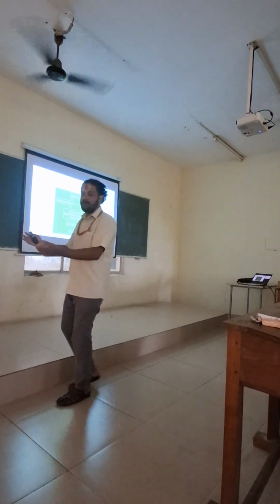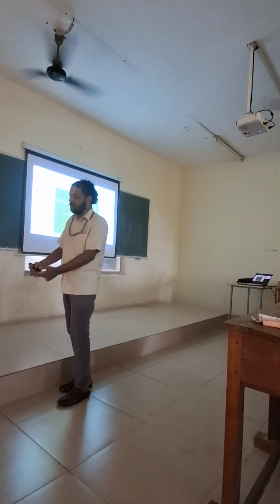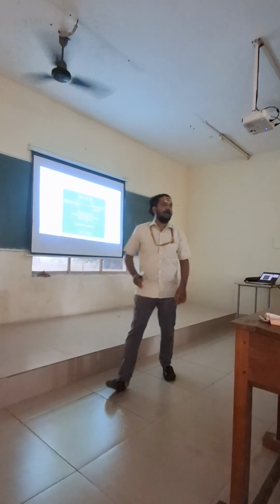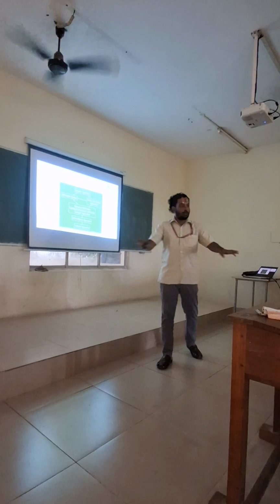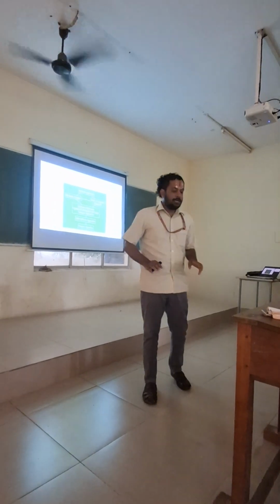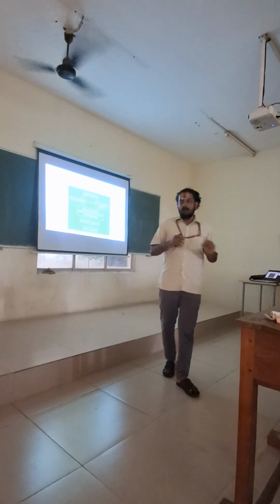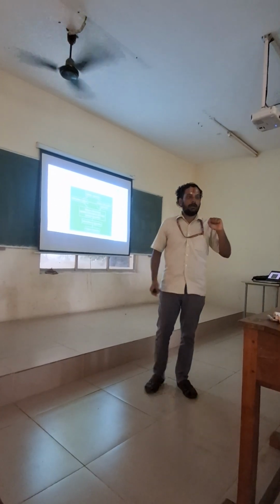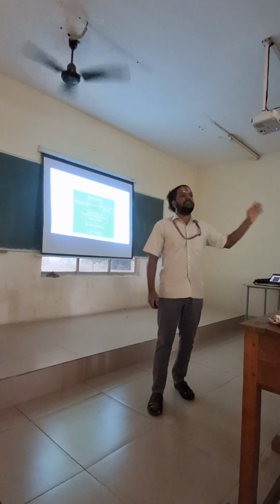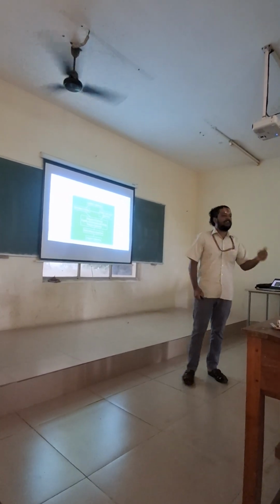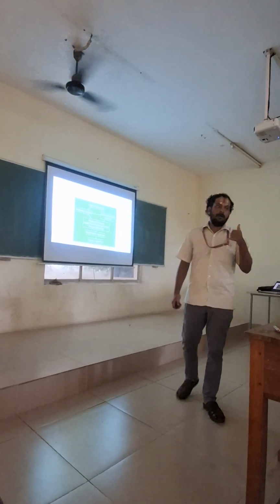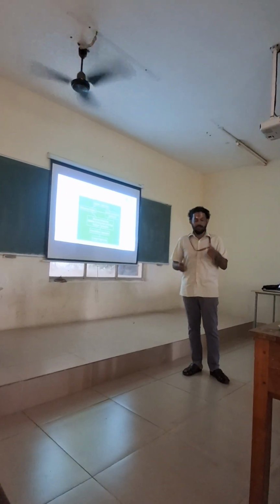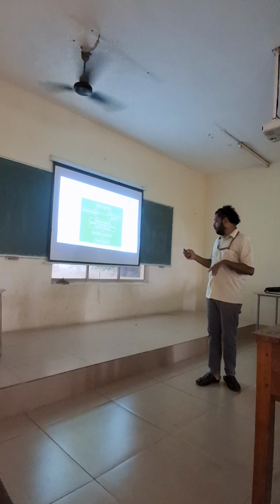I go, let's say, over here, free flight time goes here, and then scattering happens again. Let's say I go here. It happens like that. And I statistically solve for all those particles for an extended period of time and try to arrive at some kind of a polynomial regression, which will give me the overall transport of electrons in the device, in the lattice. And this is a multi-parallel approach.